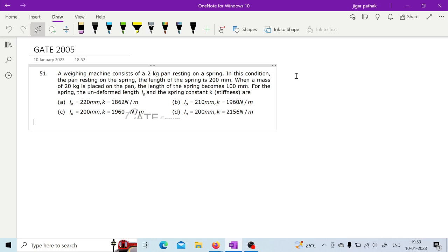From the previous problem, the total gap of 1 mm was our assumption. And in the free length equation, we are using solid length plus total gap. Yeah, in the free length equation we are using total gap. And that total gap, is it when we are considering the compressed condition or the free condition?